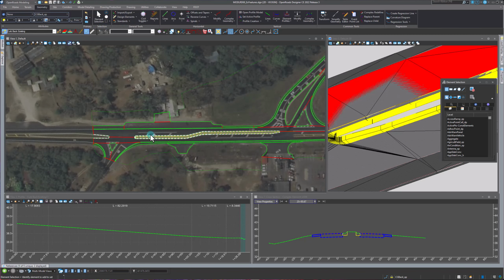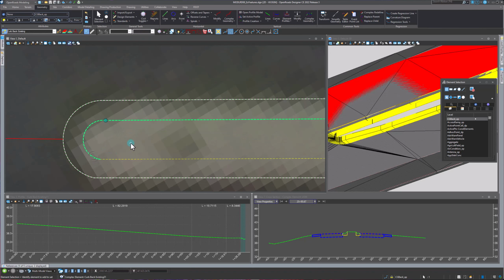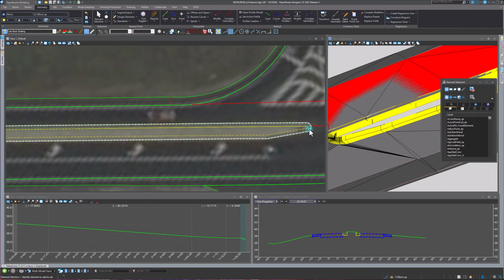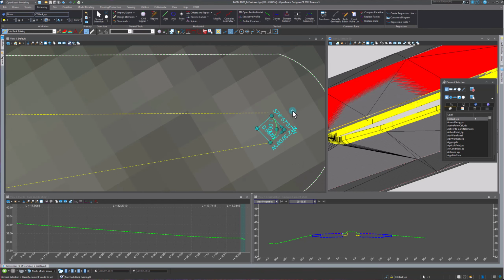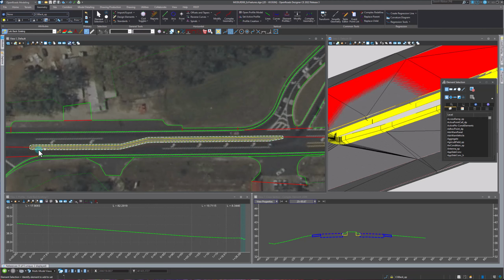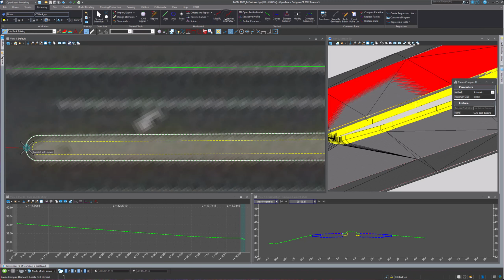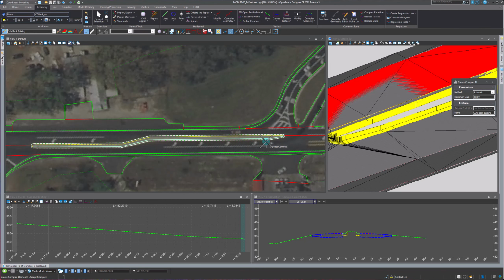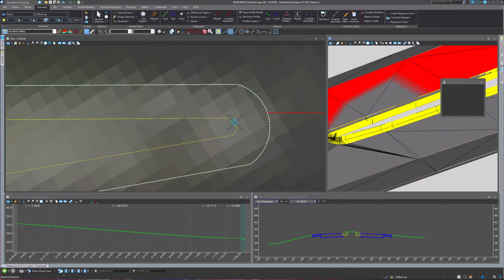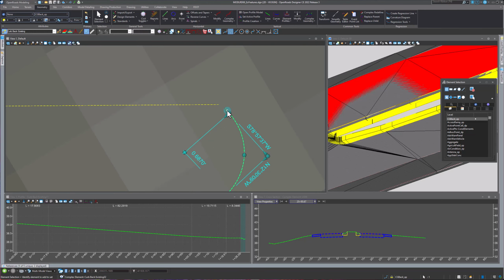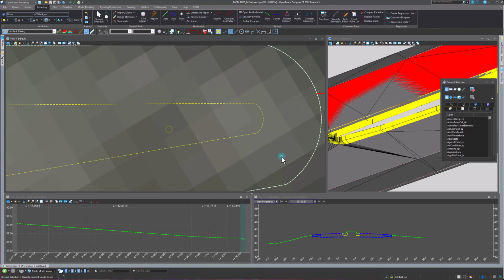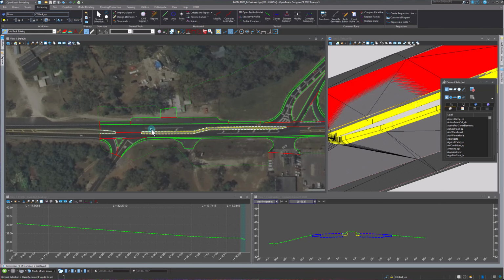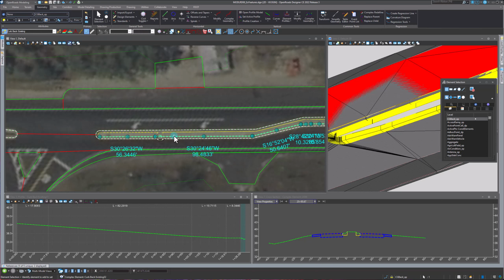I think the issue is sometimes when you get topo elements, these arcs are not arcs. They're like B-spline. There's something called a B-spline curve. That's an arc that constantly changes radius, and they're kind of a pain in the butt. So now that we have that, we should be able to complex this together. And now this arc can be manipulated, and I can just drag it up and snap it to there. So now I've got my two curb lines.